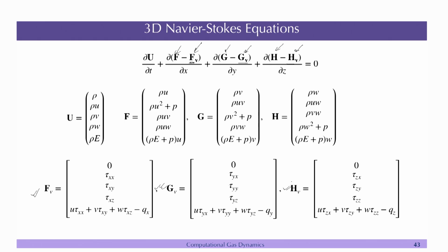I have briefly discussed this earlier. So you will have the viscous terms also acting on that. You will have a matrix of all these: tau xx, tau xy, tau xz, then tau yx, tau yy, tau yz, and in 3D tau zx, tau zy, and tau zz, and there are basically 6 independent elements, and all these stresses need to be calculated.